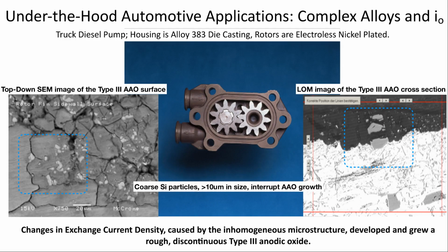The basic thing to remember is that only aluminum anodizes. Alloying elements, precipitates, intermetallic particles such as primary constituent phase that forms in castings. Anything that contains aluminum will try to anodize. The presence of alloying elements, like I mentioned when discussing exchange current density, will pose resistance and slow that reaction down.